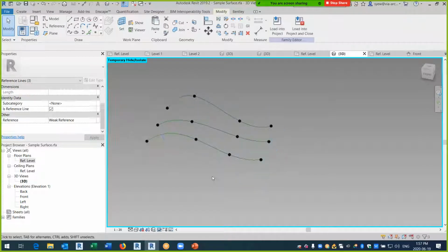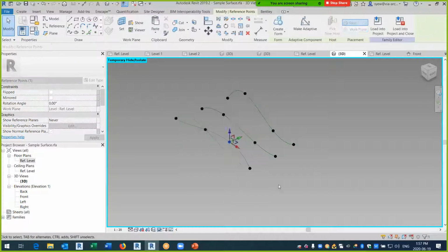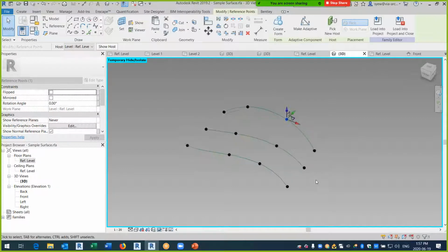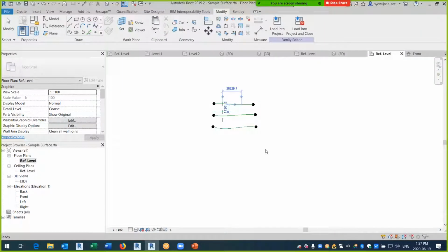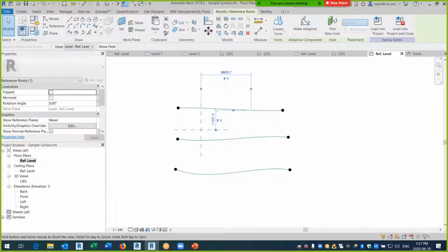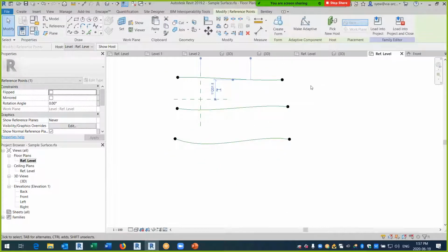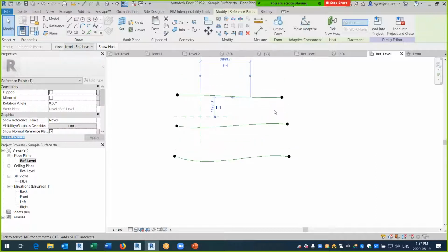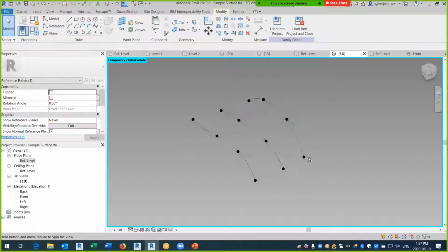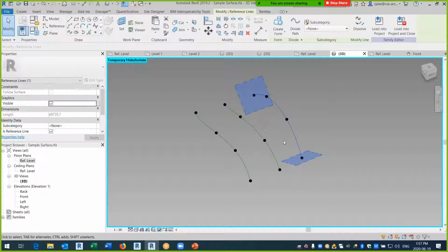Set reference. Now what you can do here is automatically readjust where you want it. What I typically recommend is that if you want to do your building like a very organic shape, you create a guideline, a grid line or something, so that you have a reference where the grid is supposed to be. And then the points, you put into those grid lines, so that those are basically your points. Once you have it, if you are free form, you don't care about anything, then just put points anywhere and you can just move your points up that way.